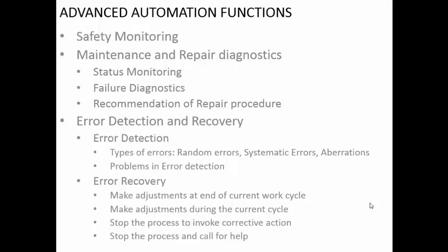Or we can have some limit switches to ensure that the carriageways or the table is not moving beyond the upper limit of that particular machine. So when the table reaches the upper limit, even though the program of instructions tells that more movement is needed, the machine will not allow it.